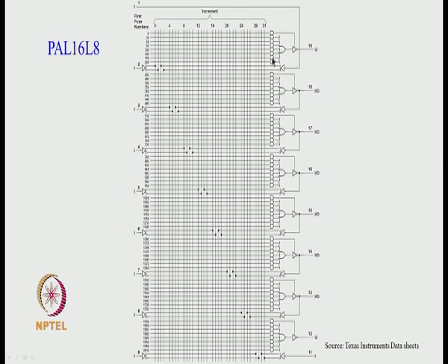For the rest of the 4 AND gates you retain all the connections, don't do any programming, and those outputs are disabled. Automatically we are doing the programming of the OR: by programming the AND gate output to 0, we are implementing the programmable OR functionality. So that's the basic idea of how to manage it if the number of product terms is less.